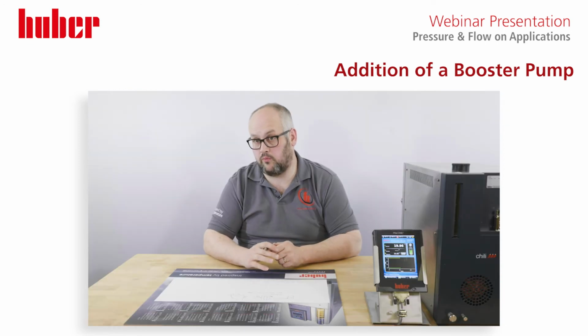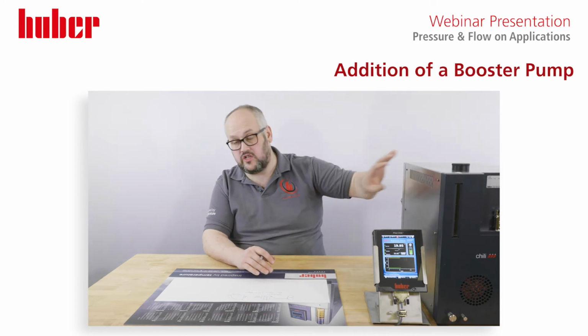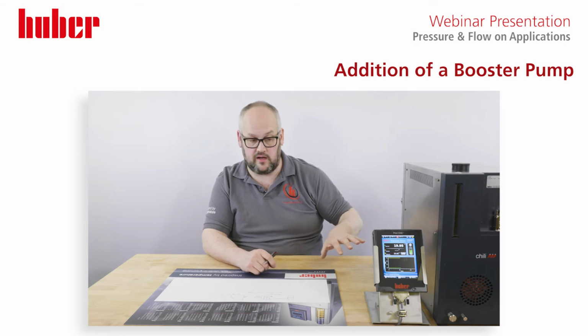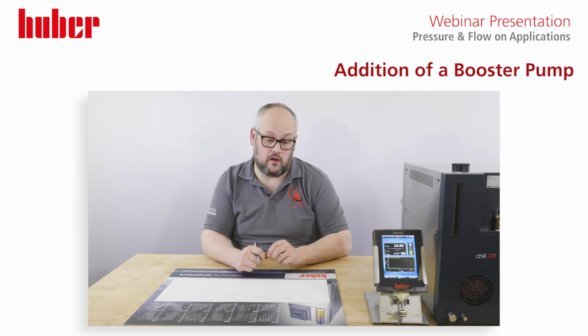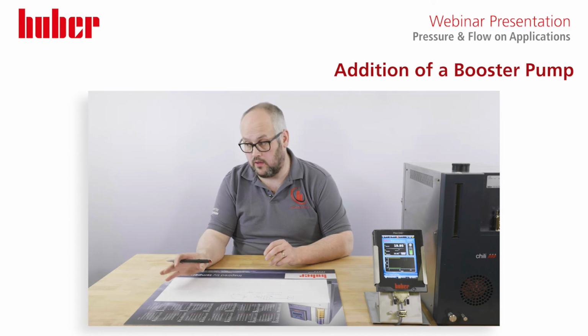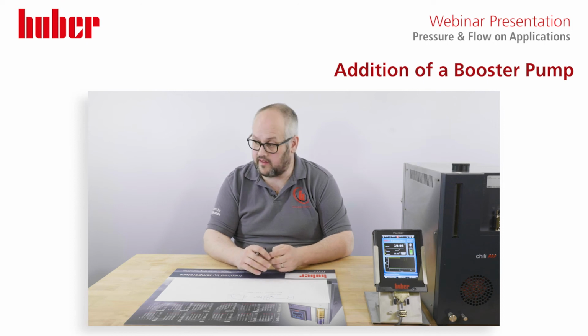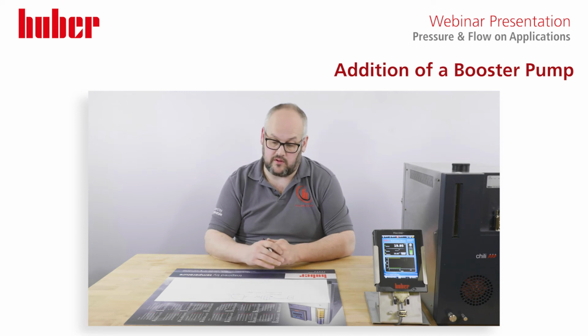A side effect of booster pumps, which we can't avoid, is that a booster pump will add heat to your system. On our Chili, we've turned off the heater on our units, so we're not applying any external heat via the heater cell. What you'll notice is there's been a temperature increase on the internal fluid temperature and the return temperature since we turned on our booster pump, because it's agitating the fluid, and in this case it's a direct drive pump. We do have some magnetically coupled pumps, but they will also add heat to the system.